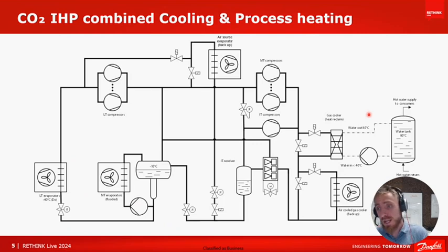Therefore, when you shut down the heat reclaimed heat exchanger, you still need to have a backup gas cooler, air cooled, the easiest, so your refrigeration system can work independently of your heating system, and vice versa. If you have part load in your refrigeration cycle, you may not have sufficient amount of waste heat for your heat pump. Therefore, you need to consider additional heat source, a backup evaporator, whether air or better water would be a source, but this needs to be accounted for.